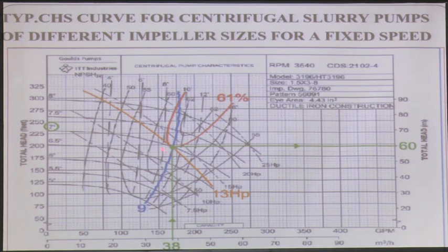So, you got to calculate that speed where it is, and people try to measure, okay, this gap is 100 RPM. That is absolutely bogus, this is not the way to do it. Use affinity law to calculate the RPM. Okay.